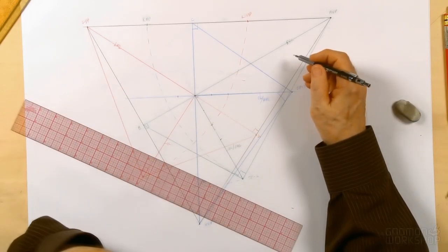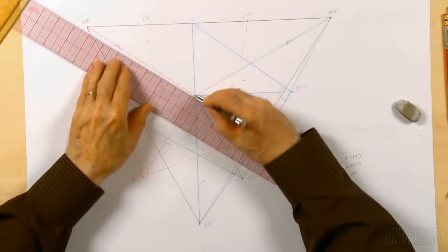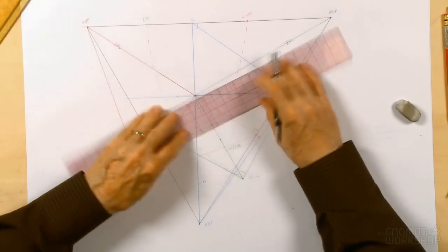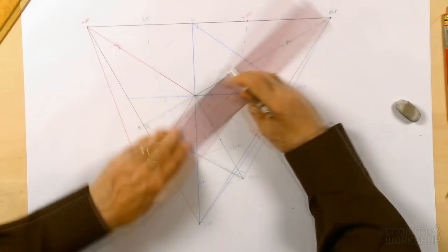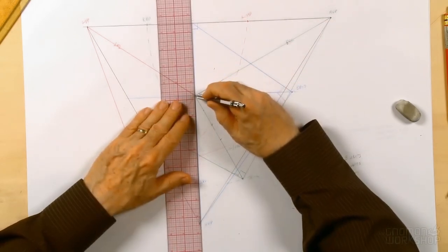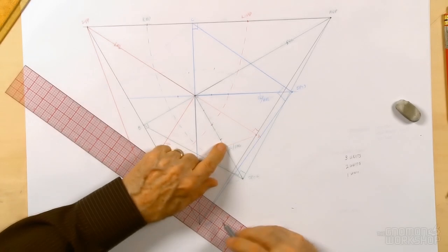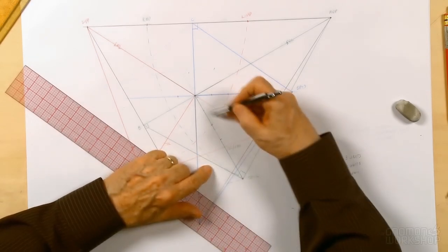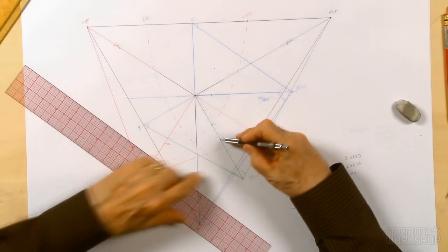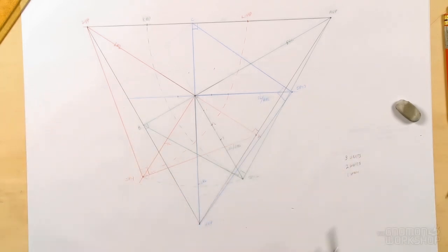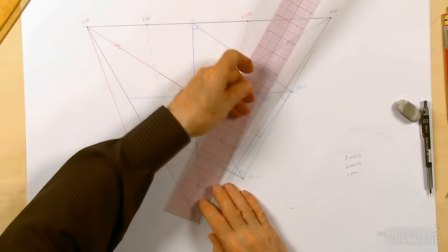Now here's how I measure things. I already know that from here, this is going to be the top of this object. So these lines here that go to the vanishing point, that gives me the top of this. I also know that this vertical blue line will be the near corner of this thing. So what I want to do is find the bottom of it. I'm going to go down 1, 2, 3 units to the bottom. From the 3, oh, you know what? I've got to get my vertical measuring point. I didn't do that yet. Excuse me. Let's get that.